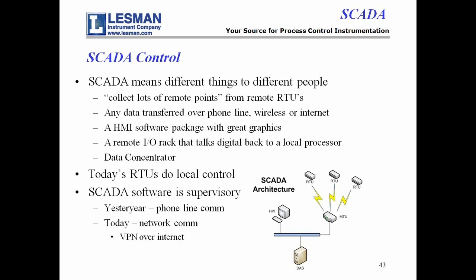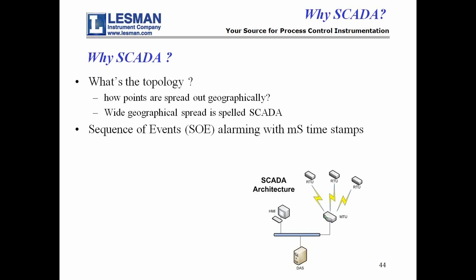So why would people pick SCADA? Well, it's basically the topology. If the points are really spread out geographically, that's where SCADA shines because SCADA puts a lot of emphasis on the communication on this stuff here between the HMI and the data acquisition system and the MTU. This is where SCADA, and also between the RTU and the MTU, they've got a lot of effort in that isn't always into just plain HMI stuff.